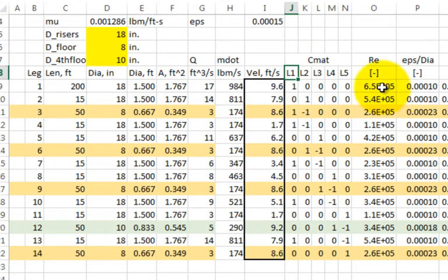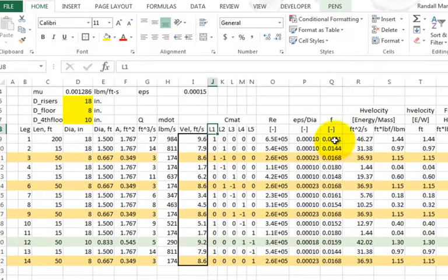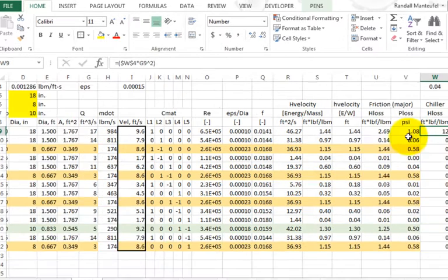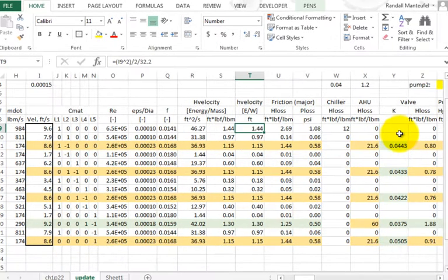Okay. Have the Reynolds number so I can get the friction factor using the Churchill equation. All right, so then you have the energy. Because this is so tricky, I always put it in 2 units, but we're going to work in energy head, this one, foot-pound force per pound mass. This is the velocity head, energy per unit weight. If you notice that these have the same units, that's the reason I highlighted that.